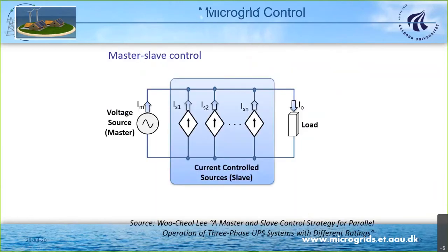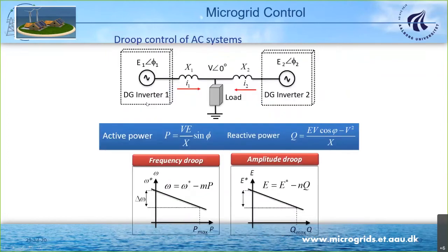So you can see just one example of what happens when we have a battery system that can, for instance, provide the voltage and frequency, and a number of photovoltaic systems that can work as current sources. These systems will be stable by definition, but the main problem is what happens when I have, for instance, a number of energy storage systems trying to fix voltage and frequency, working like voltage sources. They, of course, fight each other, and then we have to find a solution.